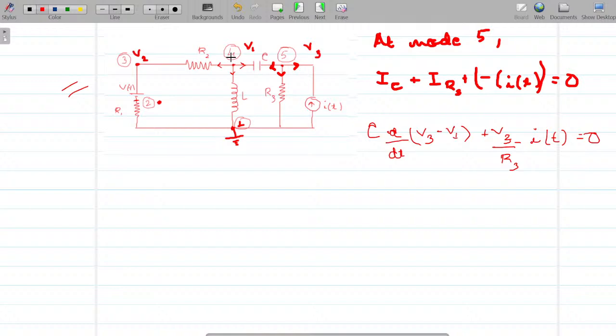Even when they're entering, you will take a minus sign. This is where you will make a lot of silly mistakes. So assume all currents to be leaving. You don't need to keep changing according to conditions. That would be easier if you stick to the plan. For now, just understand what is told so far.